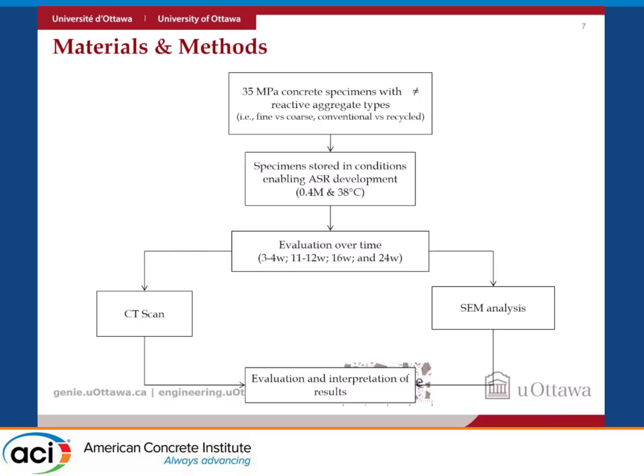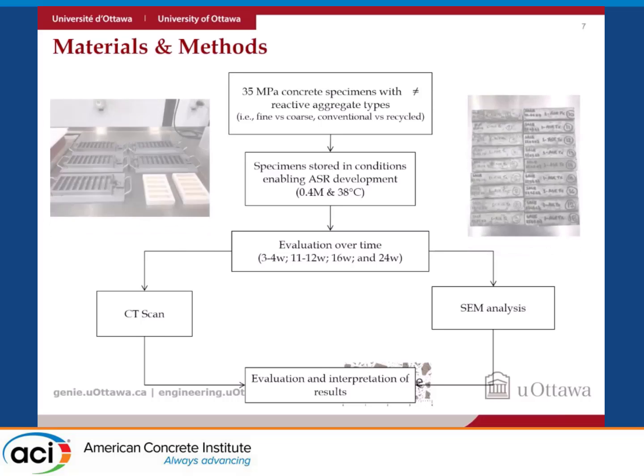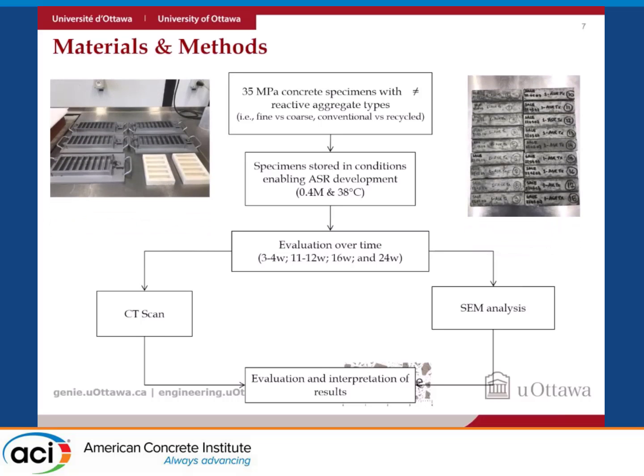So we designed 35 megapascal concrete with different reactive aggregates, so pretty much 4 families: conventional concrete with a fine and a coarse material, and a recycled concrete with reactivity in the original virgin aggregate and in the residual mortar. Then we soaked that at 0.4 molar. Why 0.4 molar?